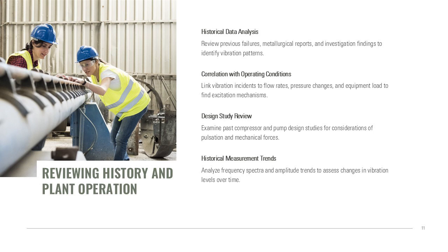Reviewing past design studies, particularly those involving compressors and pumps, can reveal whether pulsation or mechanical forces were considered adequately. Historical measurement data, including frequency spectra and amplitude trends, should also be analyzed to assess whether vibration levels have changed over time.